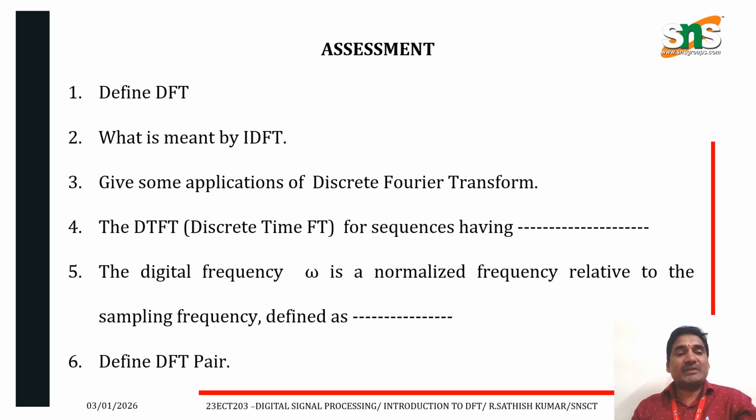Next one, we can see the assessment. Define DFT. DFT can be defined as X of k is equal to summation n is equal to 0 to N minus 1, x of n into e power minus j 2 pi kn divided by capital N. What is meant by IDFT? Inverse discrete Fourier transform can be defined as x of n is equal to summation k is equal to 0 to N minus 1, X of k into e power plus j 2 pi kn divided by N. Give some applications of discrete Fourier transform. It is used in spectral analysis, image processing, audio processing, and speech signal processing, partial differential equations, etc.